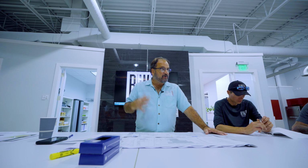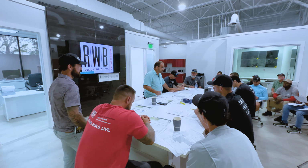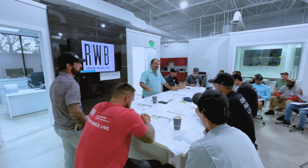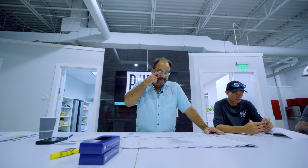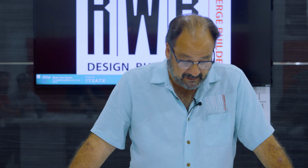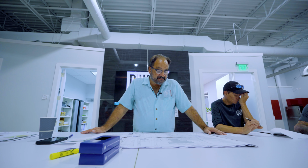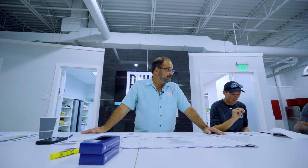The idea of all of this is twofold. One, to keep the water off the house and avoid any pressure to the house at a retaining wall or a front wall. And the second thing is to maintain all the water on the site. Okay? Those two are extremely important, and they're going to be the crux of everything we do here. Okay? The third thing that we're looking at here is a septic system.